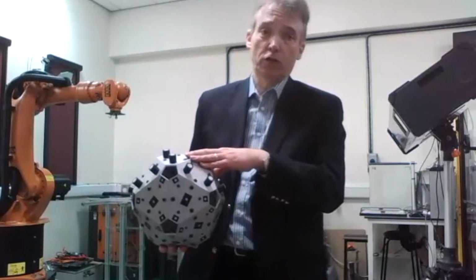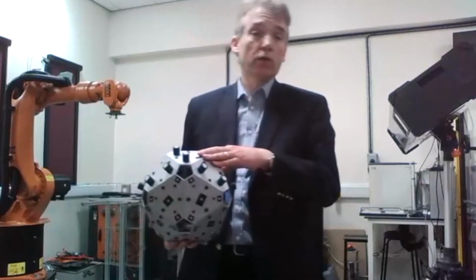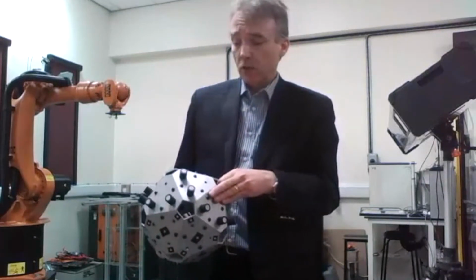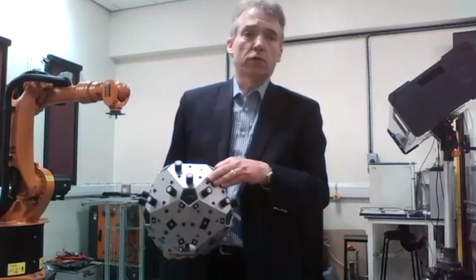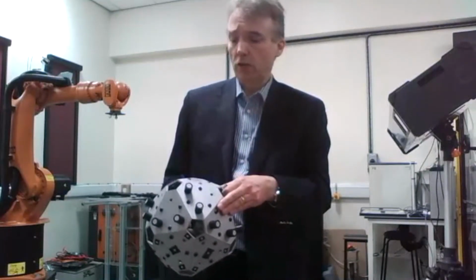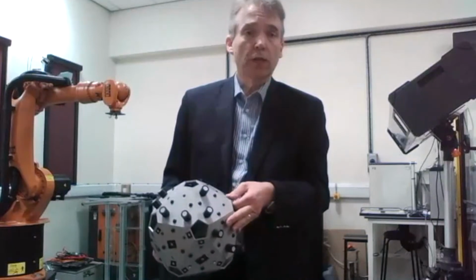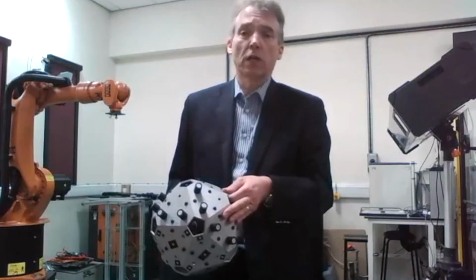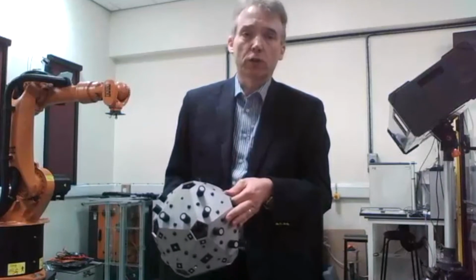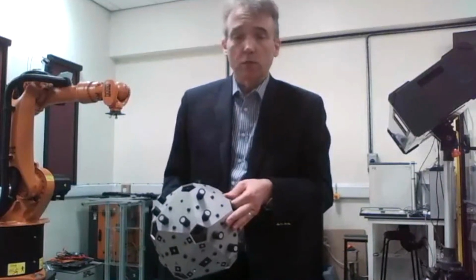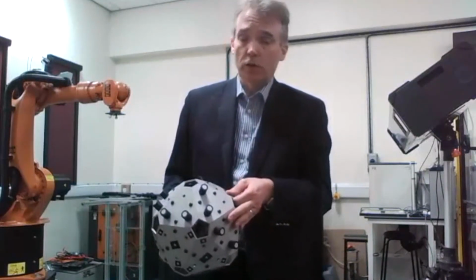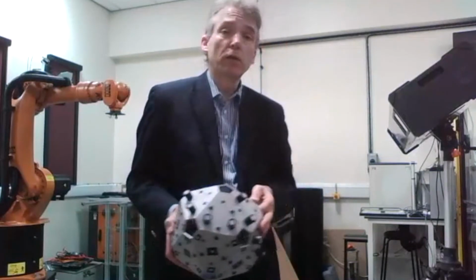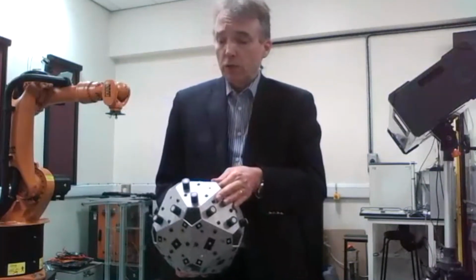It doesn't quite match up with the first scan, and so measurement error with these sorts of systems is something that we've been trying to work on, to improve the accuracy and get it close to the mechanical coordinate measuring machines, which are the workhorses of the traditional metrology lab. Typically a few micrometers is the accuracy, whereas with the scanner here you can get maybe 100 micrometers. So we're trying to improve the accuracy.